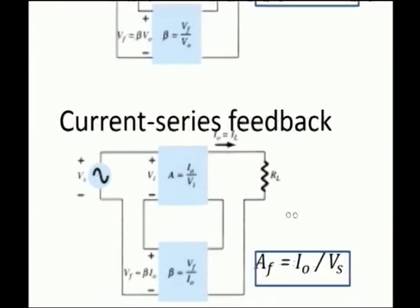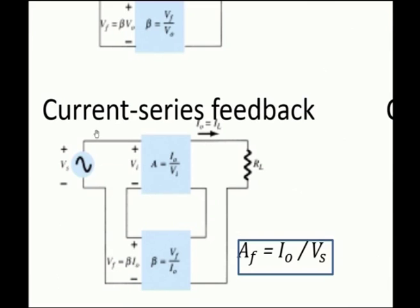And next is current series feedback. Current means you have to take the output current. Output current can be taken in series, and this is given as the input of the feedback network, and if it is a series feedback, the output of the feedback network is in series with the input voltage. So, series means the connection is also series between the output of the feedback network and the input voltage source. And what is the gain of the circuit? It is I naught by Vs. The output is the current, we have taken the current. So, I naught by Vs, where Vs is the input voltage.